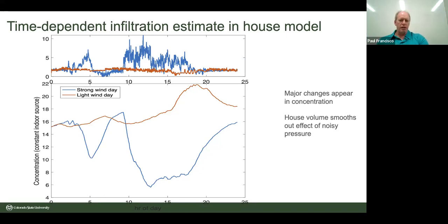Tammy, I did a quick calculation. You had that 2 air changes per hour, which I think was recirculation with the air handler, right? It is, yeah. And that's actually a relatively low number. Oh, okay. If you went up to 3 to 4, that would be probably more like what an air handler can do, a typical air handler in a typical size house. Okay. Yeah, that's the sort of thing I need help with. I just did an 800 CFM air handler in a 1,700 square foot house, and that worked out to be about 3.5. So 3 to 4 would be good.